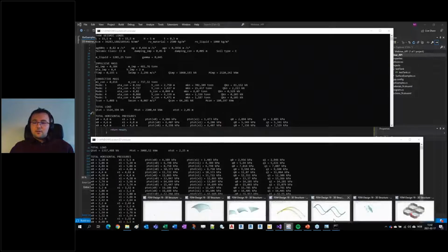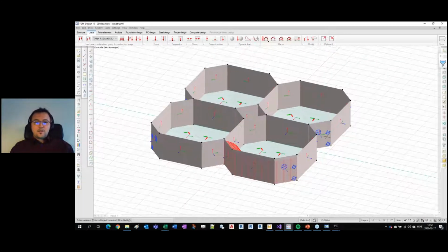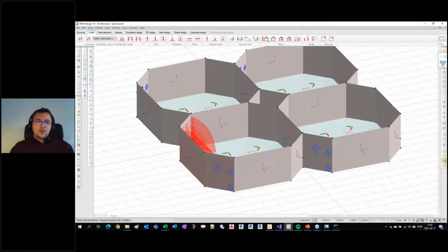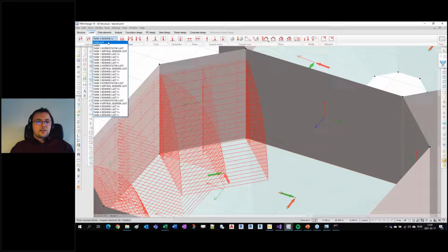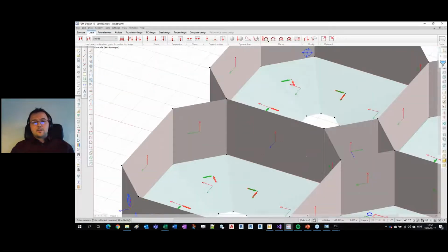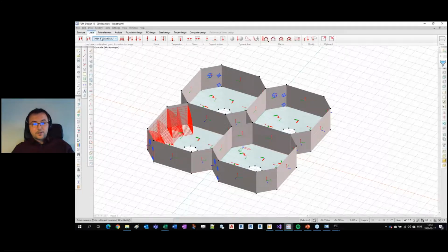So to change this model, because the walls are increased by half a meter, it's relatively easy to stretch the walls by half a meter. But to change all these loads, because they don't change only at the top, they change along the whole height of the wall, it's a more tedious task. Plus there are 16 load cases with similar loads. So one will have to do that 16 times for all directions and for all combinations of possible situations where one tank is empty, all other three are full, for example.